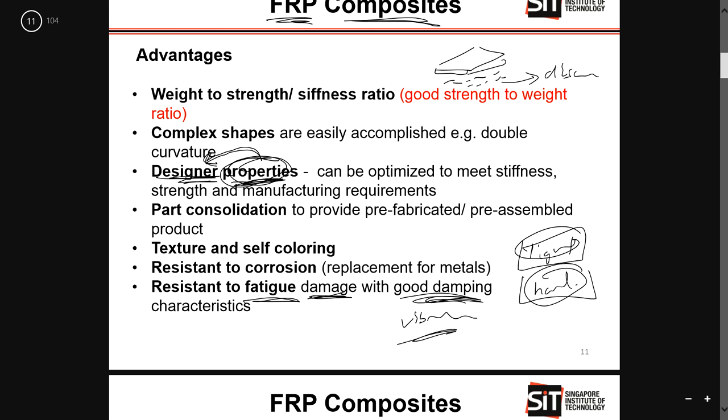If you remember, they are all by itself, one piece by one piece. So when vibrating, this piece over here, this resin will move to here, and then after that it will return back to its own position. So the vibration in the resin, in this fiber manner, the fibers actually act as a good damping to damp away all the vibrations. If you have vibrations, then you'll cause fatigue, things like that.